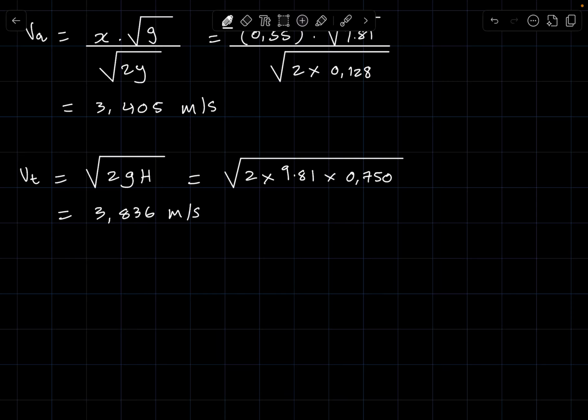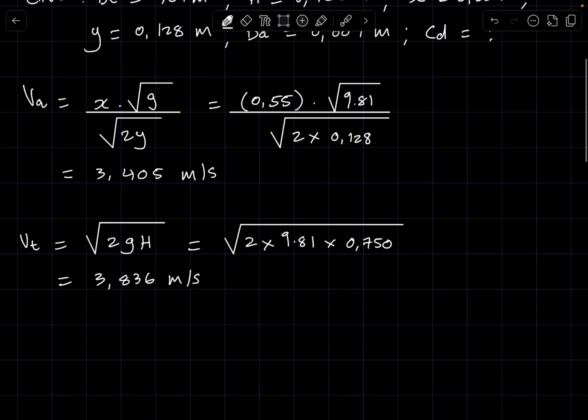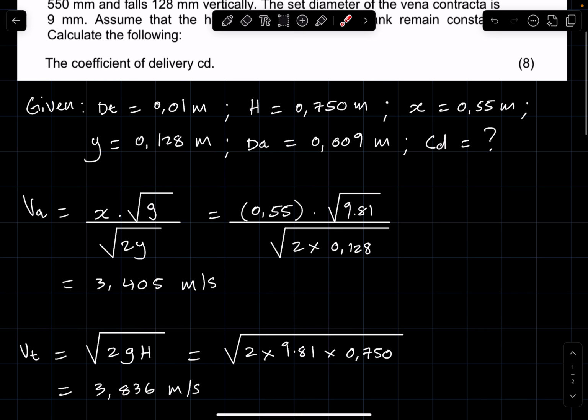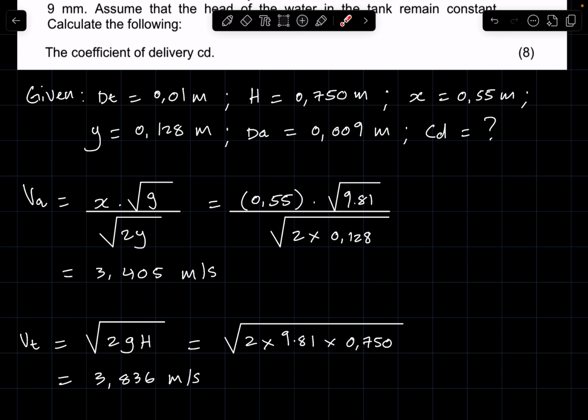Right, now this is all about having understood how hydraulic systems work, and also specifically the concept of flow through an orifice in terms of the involved quantities, that is the vertical distance of the water jet. I know students sometimes confuse the vertical distance of the jet with the constant pressure head.